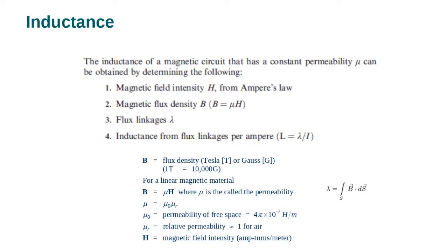Then maybe the age of the insulators also plays a role. These insulators are under high voltage, so they become weak, and you call this leakage current. So this is losses. Any current goes somewhere, it will be a loss or power loss.